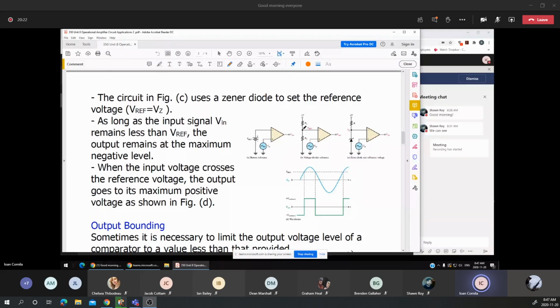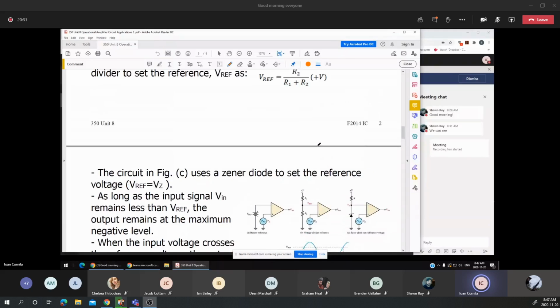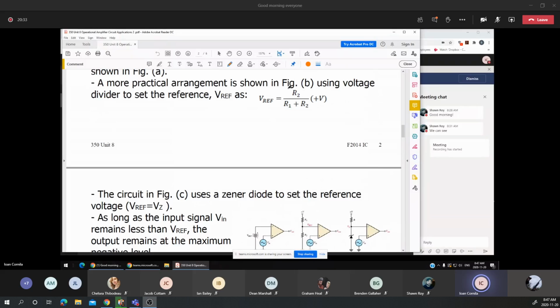The reference voltage is the voltage across R2. The voltage divider rule applied to a series circuit gives R2 over R1 plus R2. You notice that in this equation, I emphasize how to determine the reference voltage. Suppose that, as in our previous example, I choose a reference voltage of 5.25.